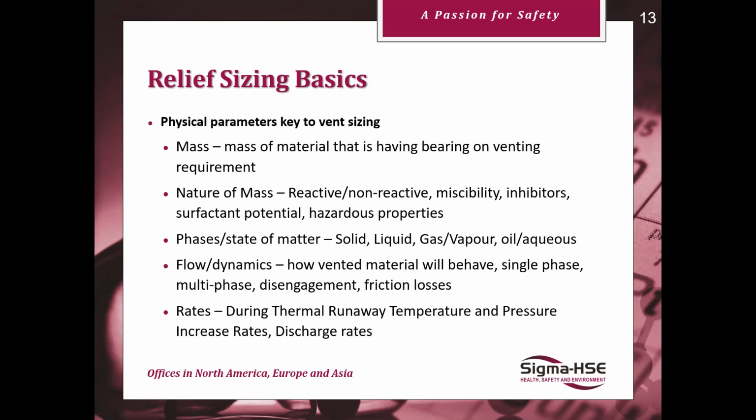So to add to that as well, once we know the worst case scenario, we know what material or reaction mass we are looking at, what is going to happen to it, what happens if a flammable atmosphere does explode at its optimum parameters, what does happen if a reactive mixture is allowed to go along the route of thermal runaway. At that point, we need pressure relief systems when you have confinement of that system.